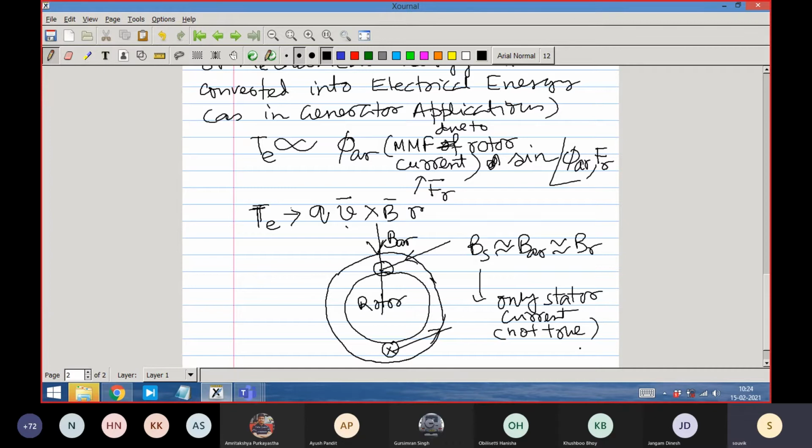This is what the magnetic structure is doing. Fluxes are not going here and there. They have to be confined within the magnetic structure. That's why we have iron and a very small air gap. We are directing the flux lines properly so that the fluxes created by the stator coils are not only linking the stator coil but also linking the rotor coil, the majority part, because we don't expect too much leakage. For simplicity, we can say full. No problem. To understand the machine in essence, you can say full.